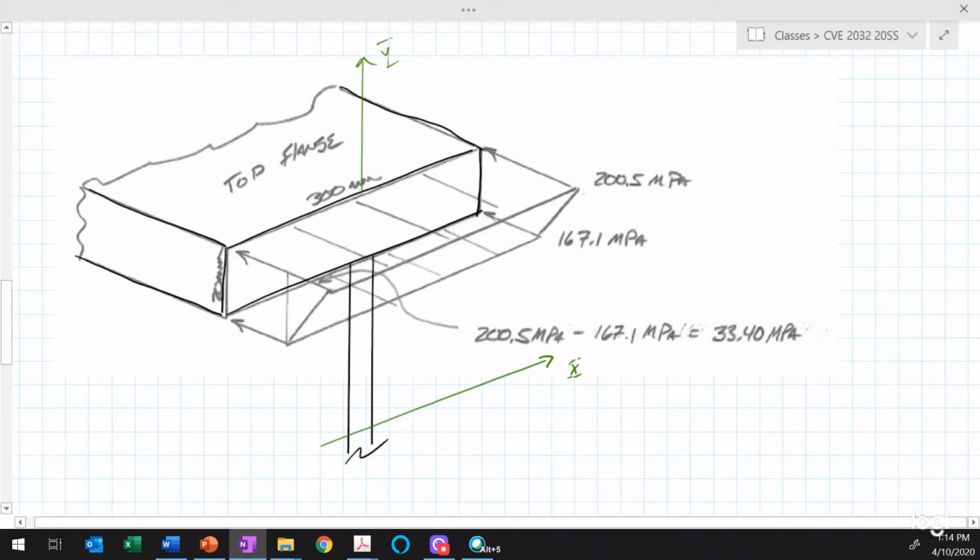So I've shown in this distribution of stress, and this is the same distribution of stress that we just sketched from the side view, or the elevation view of that girder. It's just that in 3 dimensions, it has a 3-dimensional nature to it. A lot of people refer to it as a stress block, but really it's a wedge. It's not really a block because a block is rectangular and this has a triangular element to it.